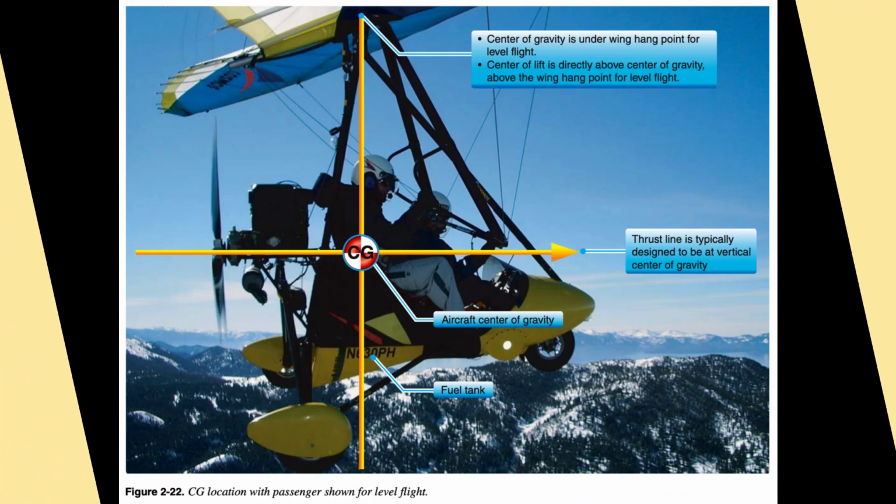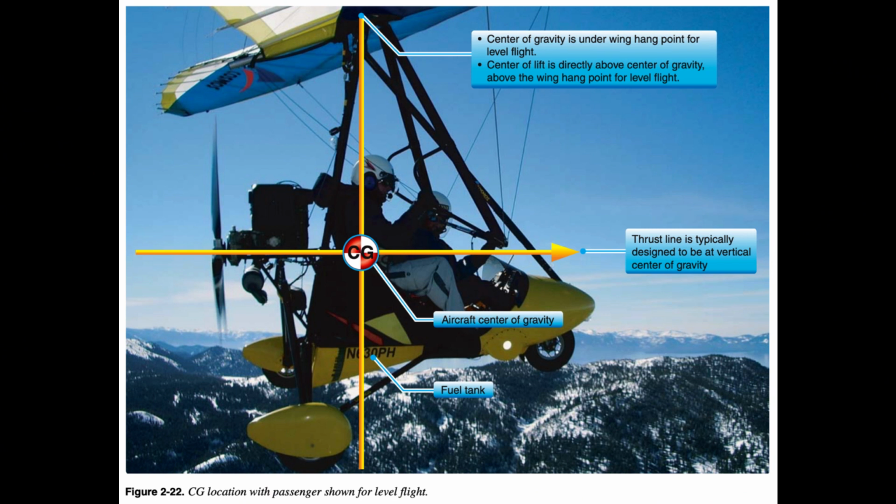Ground effect. Ground effect is when the wing is flying close to the ground and there is interference of the ground with the airflow patterns created by the wing. At the same angle of attack, lift increases slightly and the drag decreases significantly. The most apparent indication from ground effect is the unexpected lift given to an aircraft as it flies close to the ground, normally during takeoffs and landings. More details for ground effect aerodynamics are found in the Pilot's Handbook of Aeronautical Knowledge. Flight characteristics for ground effect are covered in the takeoff and landing chapters.